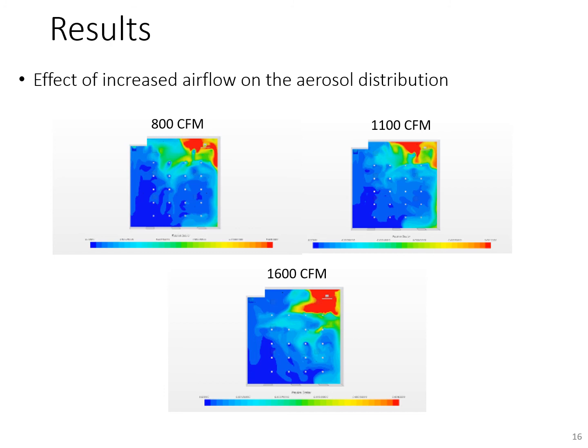Next, a set of simulations were run to conduct a parametric study looking into how the amount of supply air into the space affects the aerosol distribution from the teacher. Going back to the original classroom setup, with the teacher speaking to the south and the students facing north, it was noted that by increasing the airflow rate to the room, more airflow mixing occurred, which caused the spread of aerosols in a larger radius around the teacher.